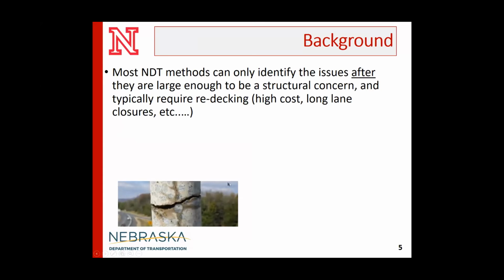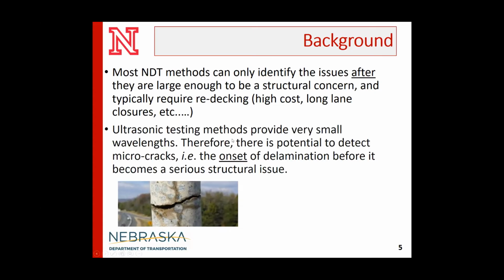So we might be all familiar with core results like this. You do an NDT test and you identify a problem. You core, yes, there's a problem, but it's a really big problem already. So eventually you would have to do something major like redecking in that situation.